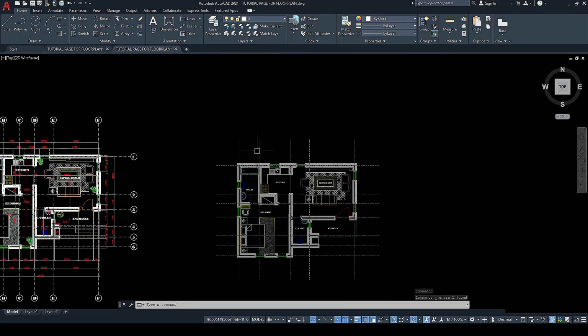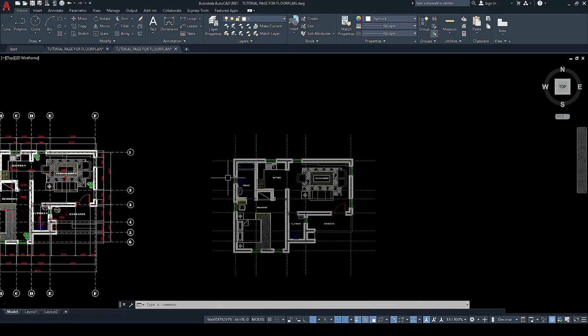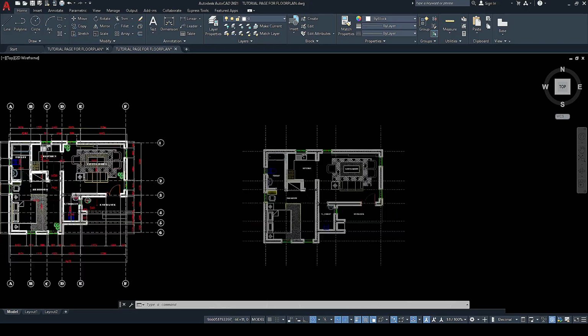The use of a grid is to give you a linear path, especially when we are doing our setting out on site. It helps us to transfer direct measurements and know the walls that are aligning in the same direction. It also adds graphics to your work and makes it look more professional and detailed.